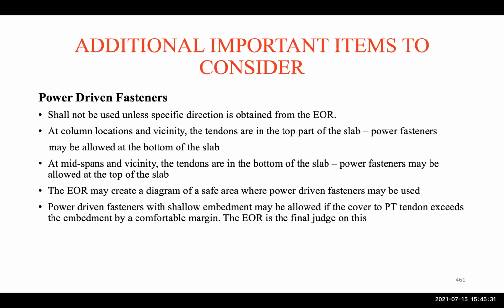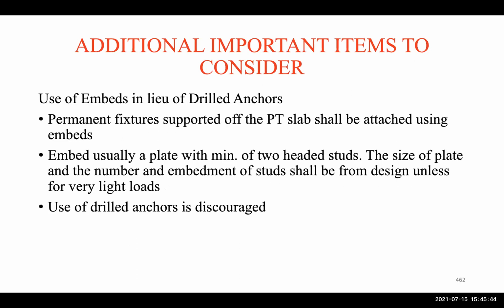Then you can maybe drill at the bottom of the floor. So this all depends on the layout of the tendons, and of course we have to consult with the engineer of record. And then use of embeds and use of drilled anchors, we talked about that.